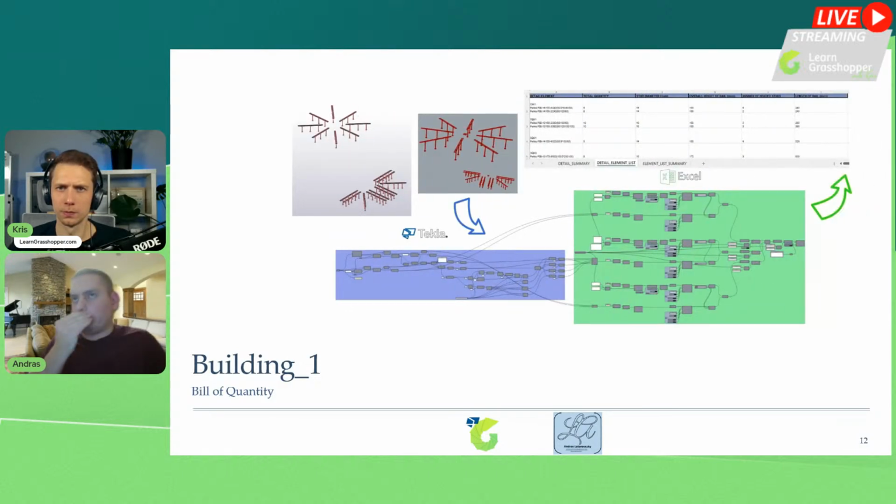After the modeling, the next step was quantity takeoff, creating lists and plan annotations. I exported the quantities to Excel. Although it is possible to create this Excel file using the Tekla template editor, I think setting that up would have taken longer. Therefore, it is simpler to write code and use Grasshopper.